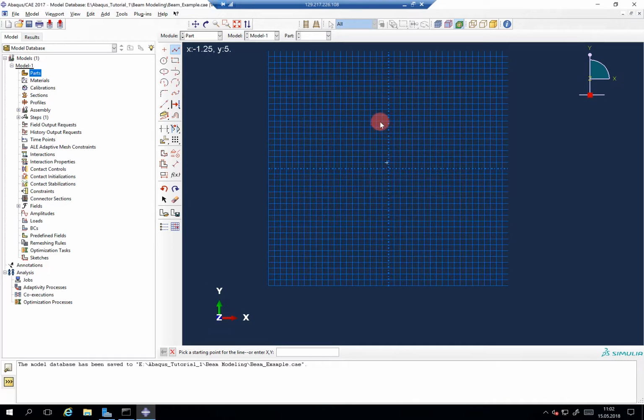We can now use our mouse to visually create this thing. However, we could also define starting and end points down here. So for example, we could go to 0, minus 50, then go to 0 plus 50 to get a height of 100. Then we go to 20, 50 to have the second feature point. And then we go to 100. Now you're probably quicker than I am.